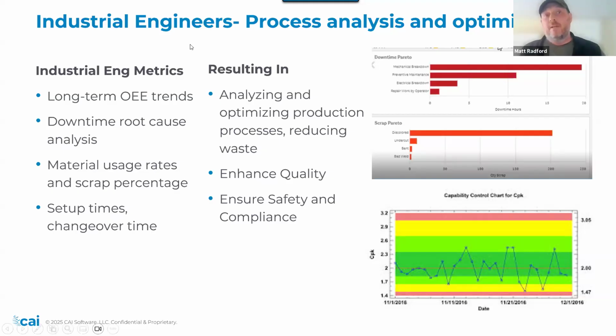And then even to go one beyond that, how are our process parameters performing, in terms of CPK and PPK and all the process capability characteristics? We can expose a lot of what the process is doing that's independent of the people and give that to the engineers that are responsible for it. So there's corrective actions, discussions, maybe some information or data that they haven't seen before that can drive continuous improvement. I find this level to be very powerful when it comes to improving your performance as an organization.